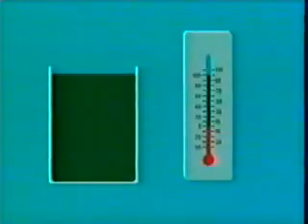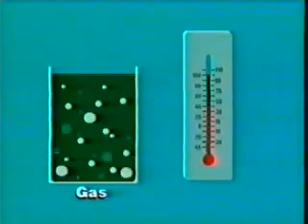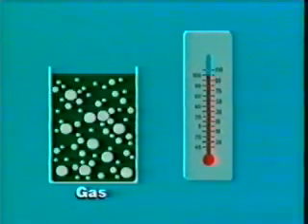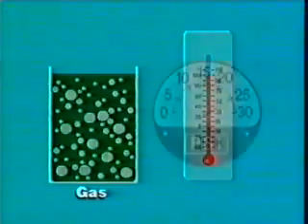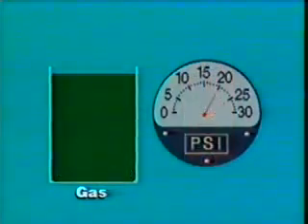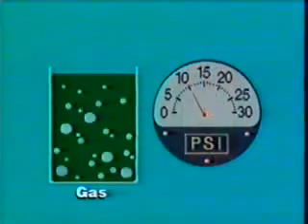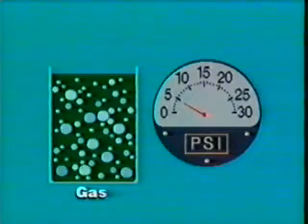Let's also review two important principles of temperature and pressure. At constant pressure, the water content of gas increases as the gas temperature increases. At constant temperature, the water content of gas increases as the gas pressure decreases.